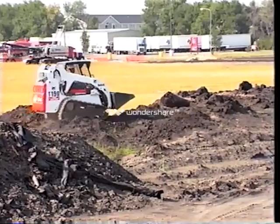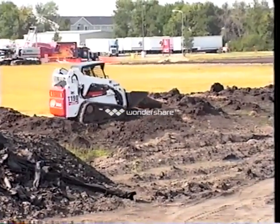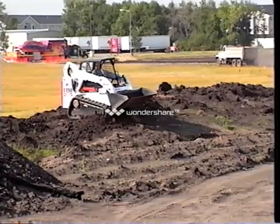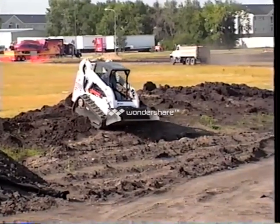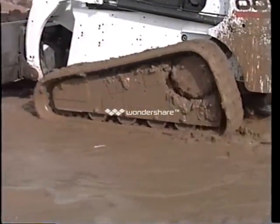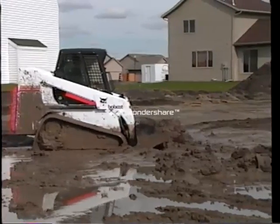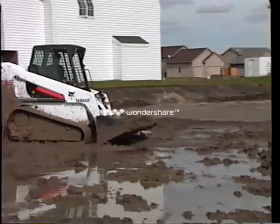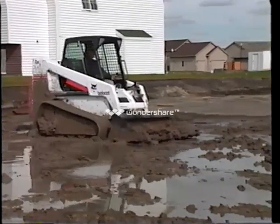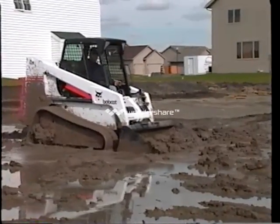Because tracks distribute the loader's weight over a larger area, they deliver a smoother ride by carrying the machine over the top of rough terrain and obstructions such as ruts, potholes, and soft ground. When operating in loose or soft ground conditions or wet, slick surfaces, the tracks provide more ground-to-surface contact for increased traction. The compact track loader can keep pushing a load when the wheels of a rubber-tired loader might simply spin in place.